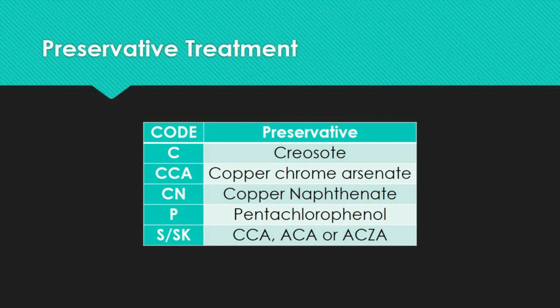Now, the Canadian standard CSA O80 and the American Wood Protection Association standard T-4 both address the preservative treatment of wood poles, which includes pushing preservative into the wood. Now, these standards have the same technical substance, and the treatment techniques are either going to be oil or water-based. The criteria specify the amount of preservatives that must be placed in the sapwood, as well as the depth to which the preservative must enter the sapwood.